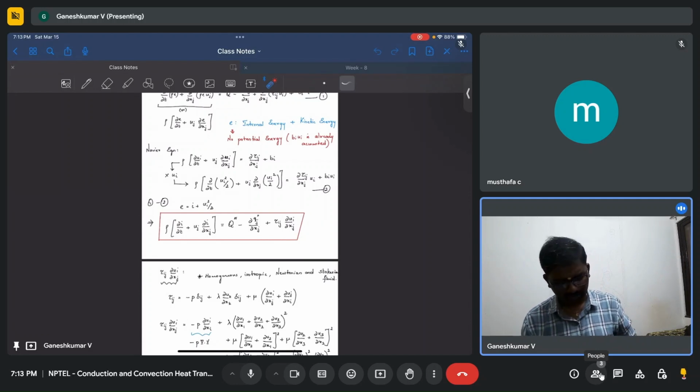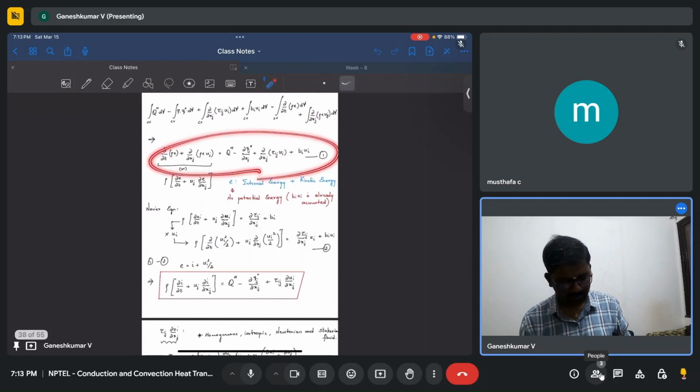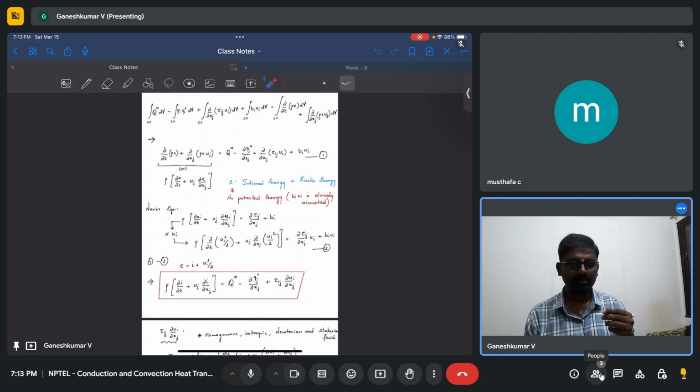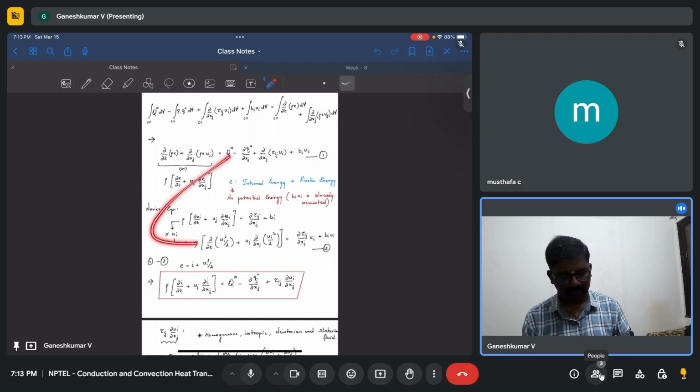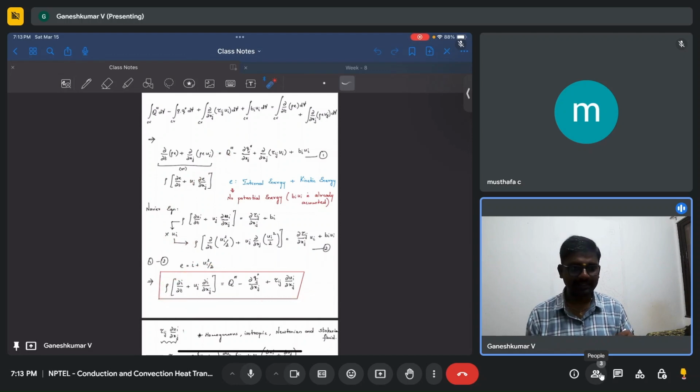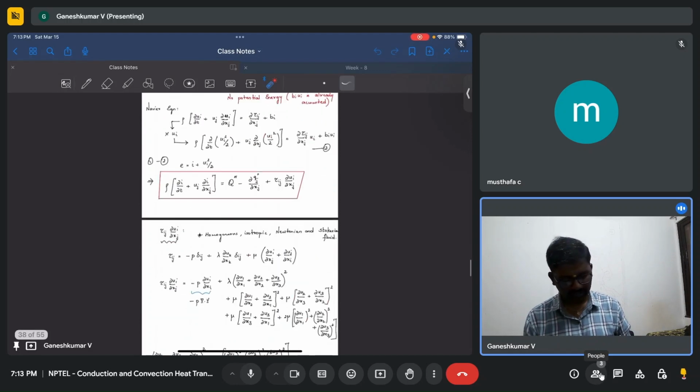In fact, you will end up having this total energy equation, and you want temperature, which you can obtain from internal energy. So we try to read this: total energy contains only internal energy and kinetic energy. To get kinetic energy, we take the momentum equation dot product with the velocity. You will end up having the mechanical energy equation. You subtract the mechanical energy equation from the total energy equation, and you will end up having the internal energy equation. Okay, this is where I think we stopped.